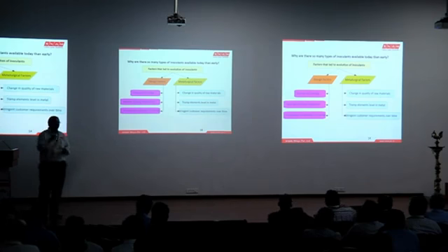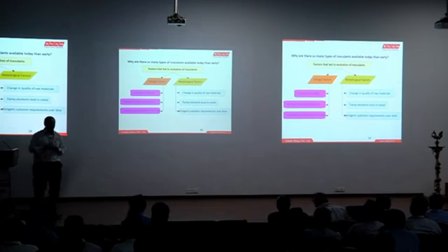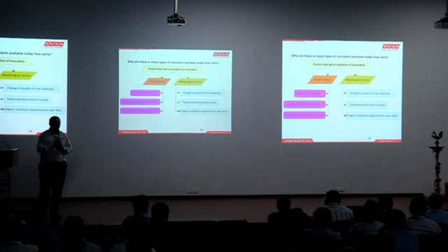Or when you have a machine shop attached to your own foundry, we start using borings, because we get alloying elements back into our metal. So the requirement of ferroalloy addition comes down. There are a lot of factors involved in altering the charge mix to get the same quality.